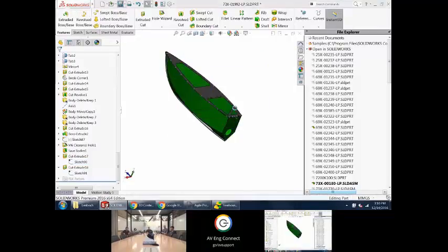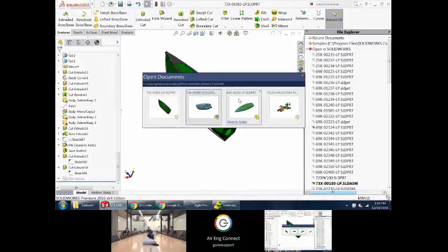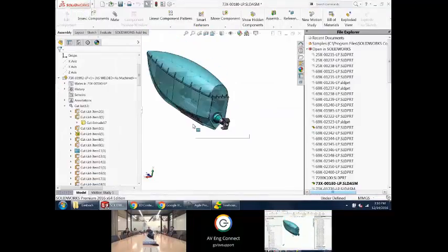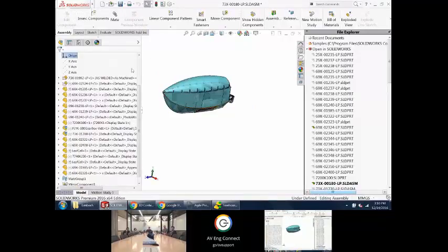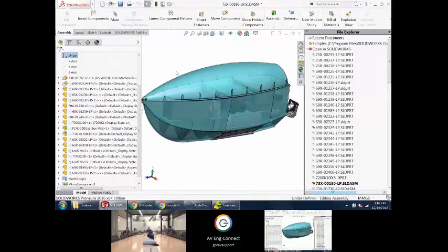So like I said, there's three styles of in context. You can just change a dimension inside of a part that's already existing. You can grab geometry from it as long as you remember to go and get rid of it. You can also build a part right in the assembly. So this is called top-down modeling.